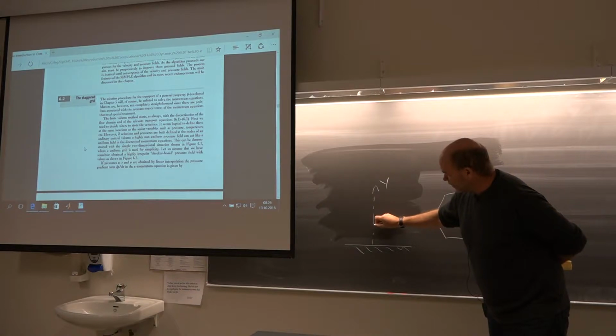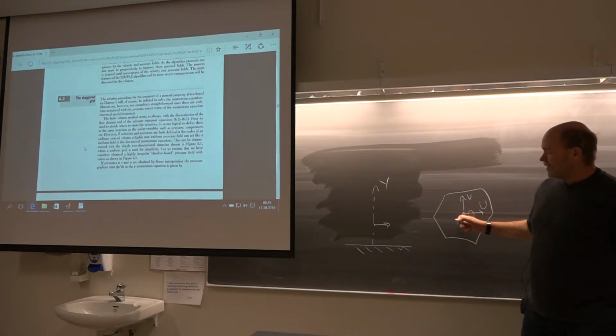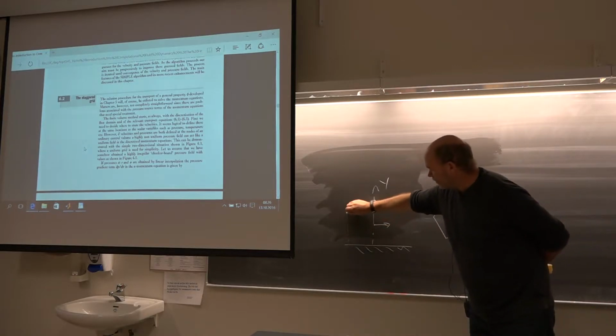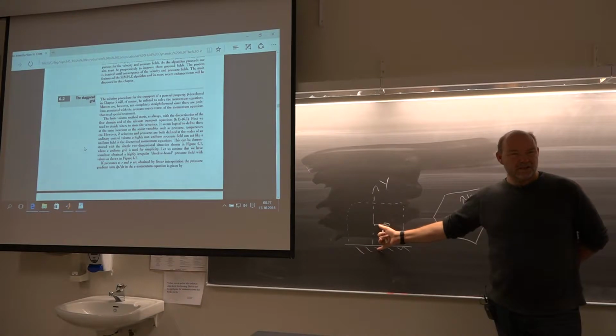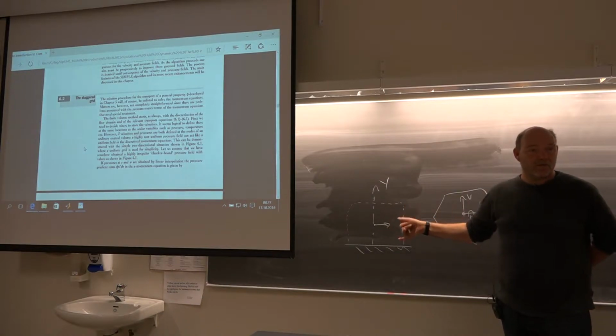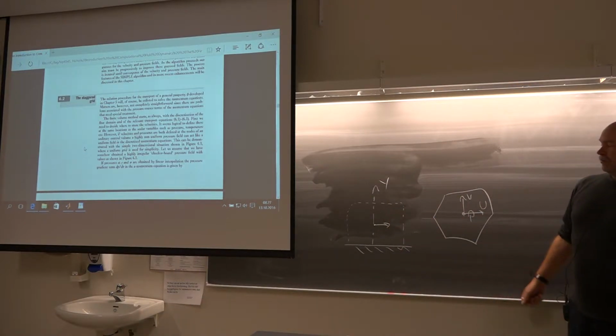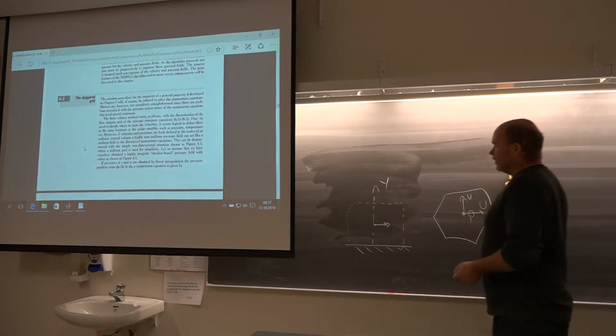Well, the first velocity alongside the wall is going to lie in the cell center. So if you have a cell here, okay, then the distance to the first velocity close to the wall will be delta y half in meters, which you then need to calculate the y plus and so on. Of course, this can be done for you in OpenFOAM.